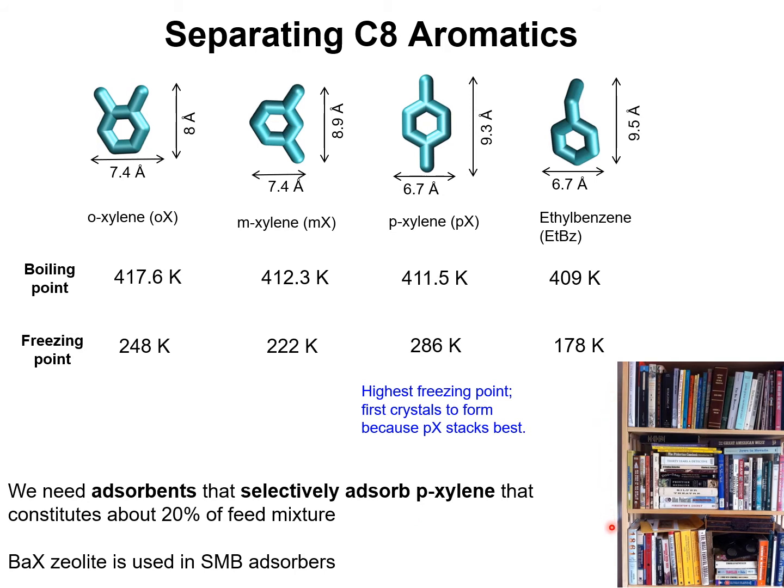The picture here is just to demonstrate that the separation of C8 aromatics in an adsorption device requires us to recognize the differences in the packing efficiencies of the C8 aromatics within the crystalline framework.